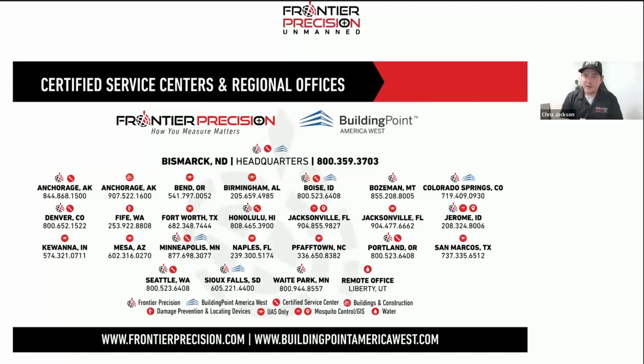Yeah, I think I mentioned that earlier. So in a single flight line, we're covering about 140 meters of ground at a time, so almost a football field and a half. In a single day with ideal conditions and minimum takeoff areas, being able to fly at just under 400 feet, so you're not busting that cap, and being able to fly at 10 meters a second, you can really cover some ground.